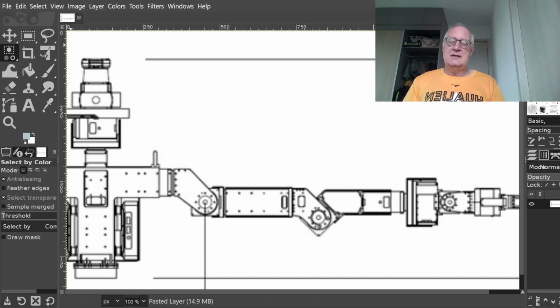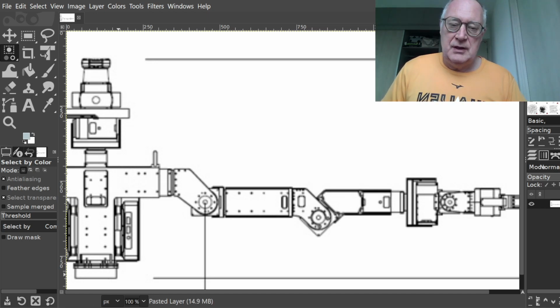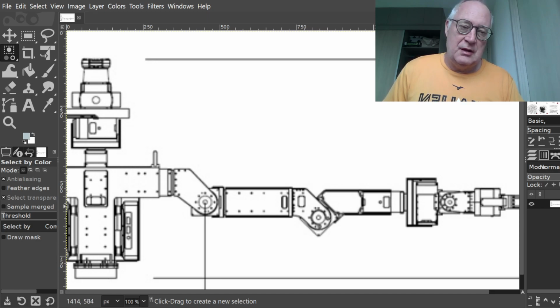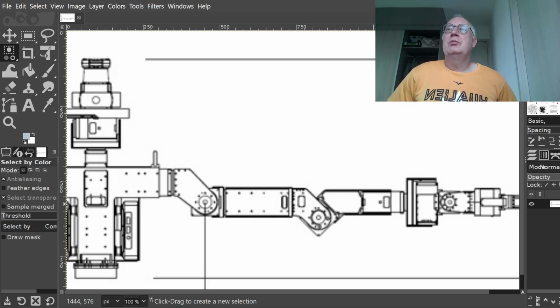First, of course, you have to identify the joints too, how many joints there are. We ignore the torso joint, we're past that already, so we have 1, 2, 3, 4, 5, 6, 7 joints in the left arm. The last one here is the gripper. So this would actually be a translational joint. We ignore that for now, so we only deal with the 6 servo motors.